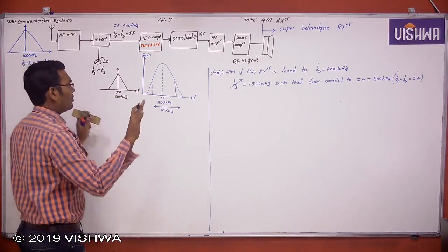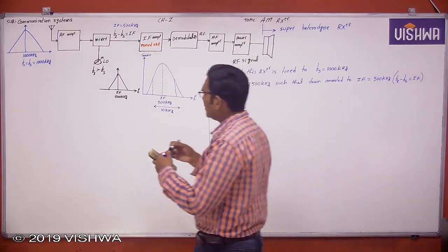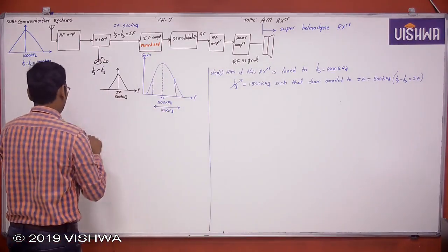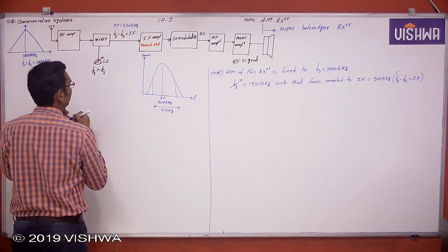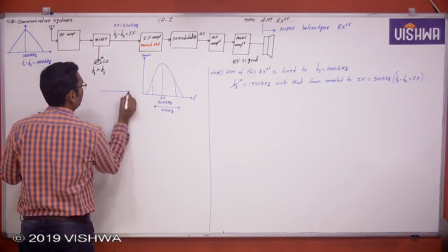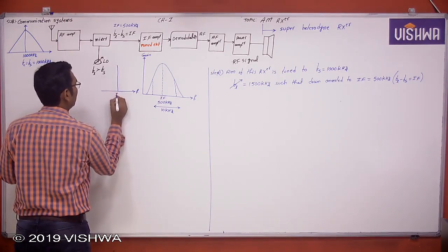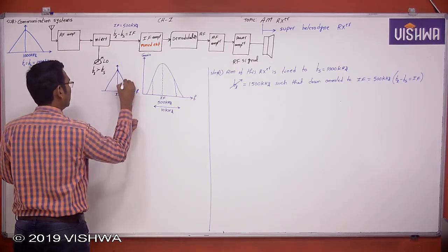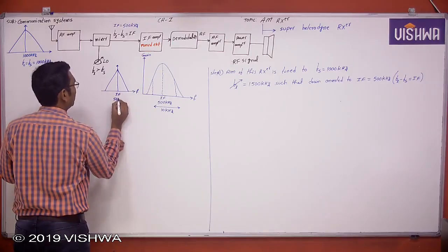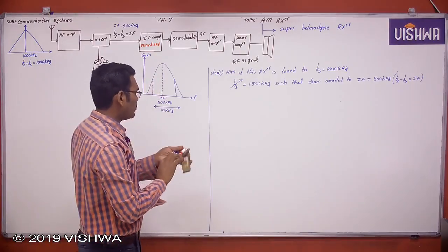Okay, now the first step is completed, right? Now this is the first step. The incoming signal is down converted to IF by adjusting the local oscillator frequency. Now step 1 is totally done, I just wrote it with a blue line such that you can easily understand. 500 kilohertz. Clear? Now what happened? Now step 2.